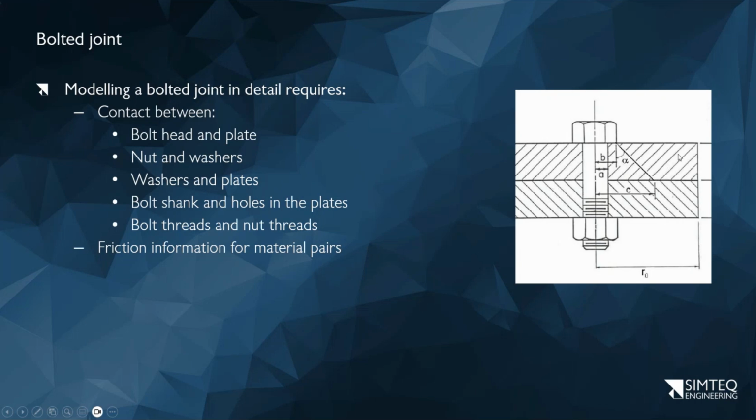So in other words, let's say I preload this. If I load this one to the right, and I constrain the left-hand side, most of that load will be transferred from there to there through that interface, which is in friction where it transfers the load. So I need that correctly. I must have the plate elements modeled in solid if I want to model using the preload, because what makes the preload work is a through thickness stress. And the only element that has through thickness stress is a fully solid element. So if I need to model this, it becomes a pretty expensive simulation. I cannot use shells for this if I need a preload, at least if I need a preload in the simulation.